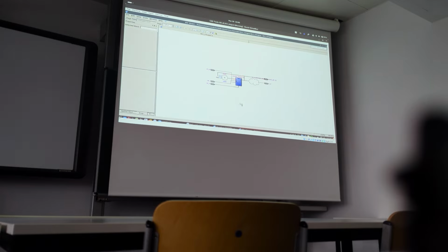If we click on the logic cloud, it tells us, hey, there is an incrementer here, just an adder implemented, and if you look at the second operand, zooming in, it tells us the second operand of our adder is just a constant 1, 4-bit wide hexadecimal 1. That's the notation, as we expected.